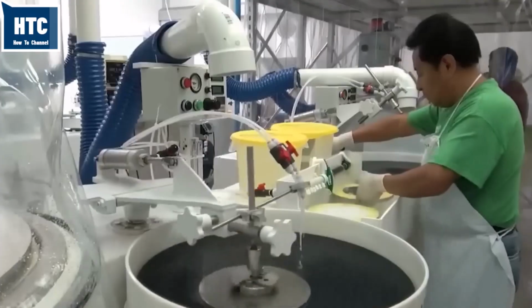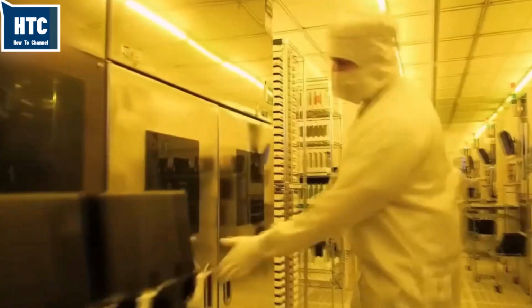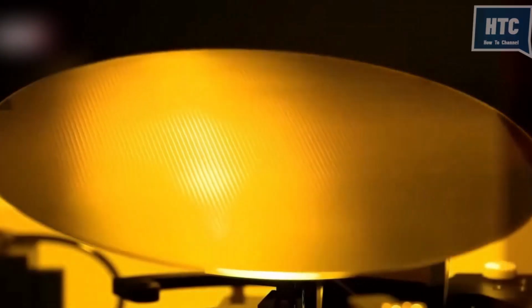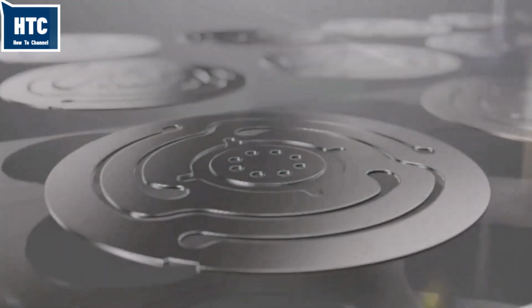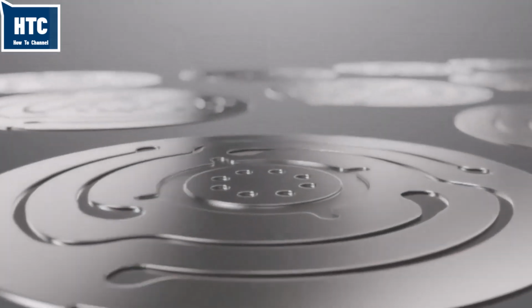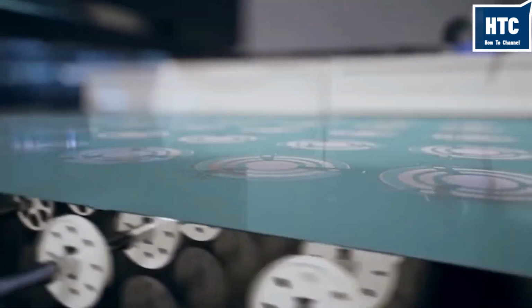A developer solution washes away the exposed photoresist, leaving a physical stencil on the wafer. Now we etch. Using reactive ion etching, the wafer is bombarded with plasma. The plasma eats away the oxide layer, effectively only where the photoresist has been removed. This is anisotropic etching, meaning it cuts straight down vertically, creating deep, perfectly distinct trenches without widening the hole. Once etched, the remaining photoresist is stripped away. We now have the physical shape of our circuit components carved into the oxide.